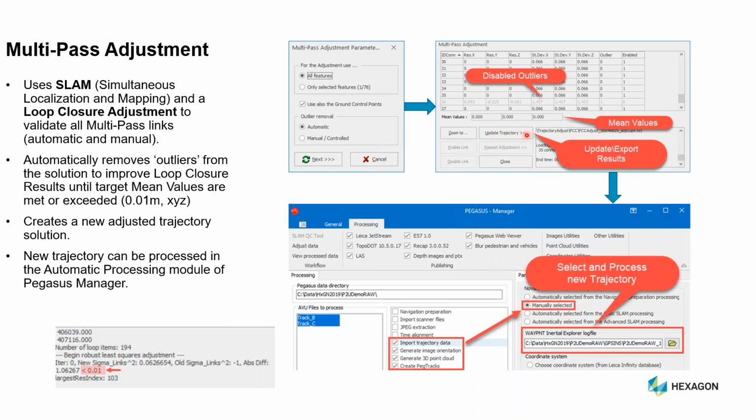So when we update the trajectory, this is going back to the initial session that we participated in together when I talked about the snake skeleton, right? I talked about how the skeleton of the snake we can think of as the trajectory, and the ribs of that skeleton we can think of as the LiDAR and the images. And anytime there's an adjustment to the shape of that spine, all the ribs are going to move with it. Well, that's really what's happening with the trajectory adjustment. We're updating the trajectory based off of its position relative to known points.